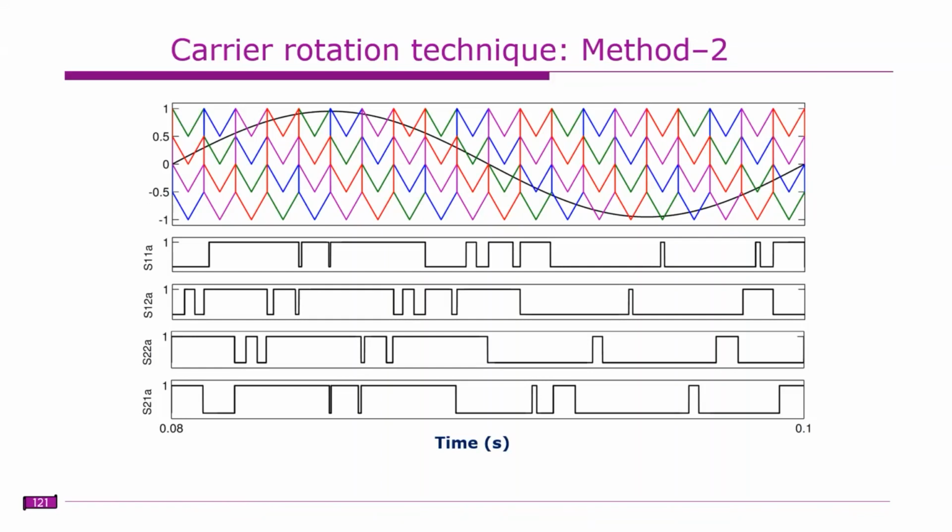If you notice, in one fundamental cycle, if you calculate the time periods or the frequency of all these, they remain the same. The conduction periods remain the same, and the switching frequencies also remain the same for all the switches. Therefore we can expect the advantages of phase shifted PWM, that is capacitor balancing or even power distribution of the DC sources. So that is possible.